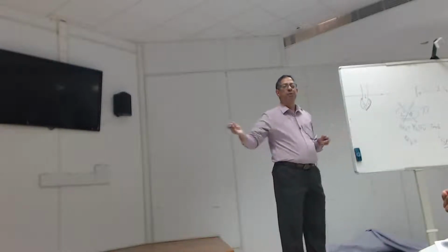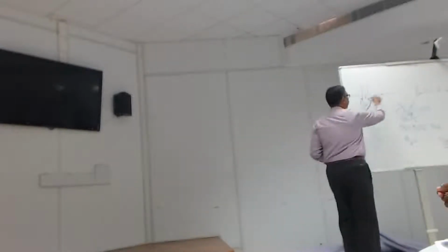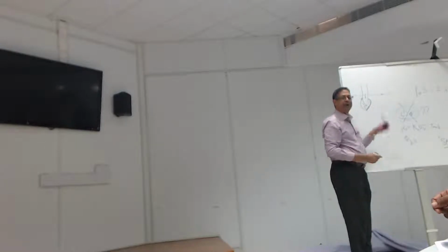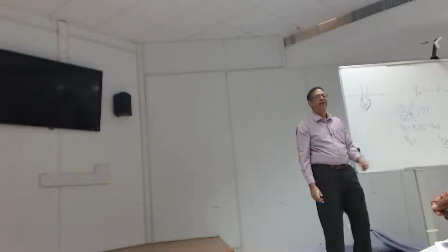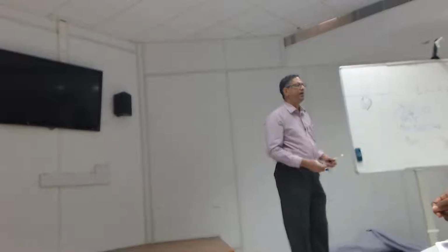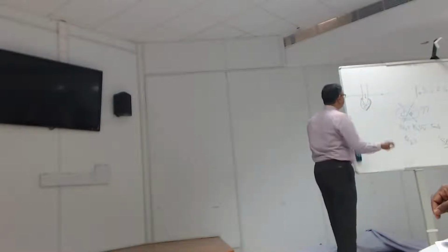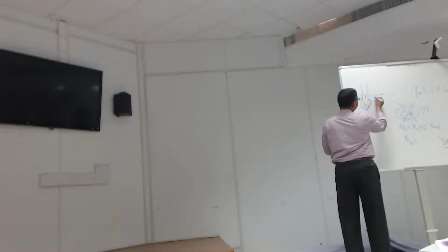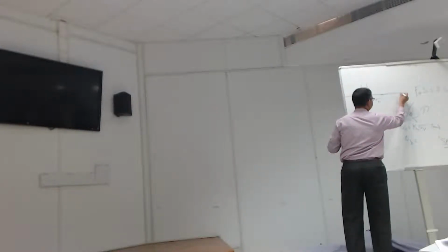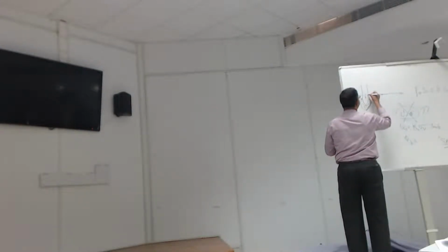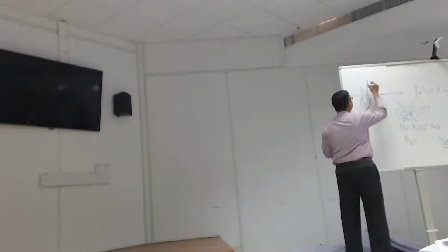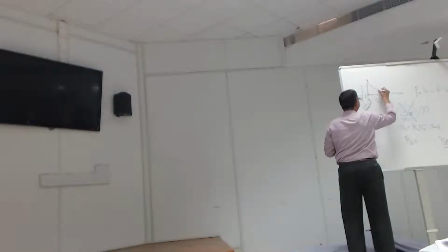There obviously must be a boundary. I mean, if it is 10 diameters away or 20 diameters away from the pile, the soil doesn't know there is a pile that has been driven far away. Whereas next to the pile, of course, the soil will feel a hell of a lot of horizontal stress. So he basically said, if I'm plotting horizontal stress along this axis, his assumption was that it will be highest here, some value, and it's going to decay exponentially.